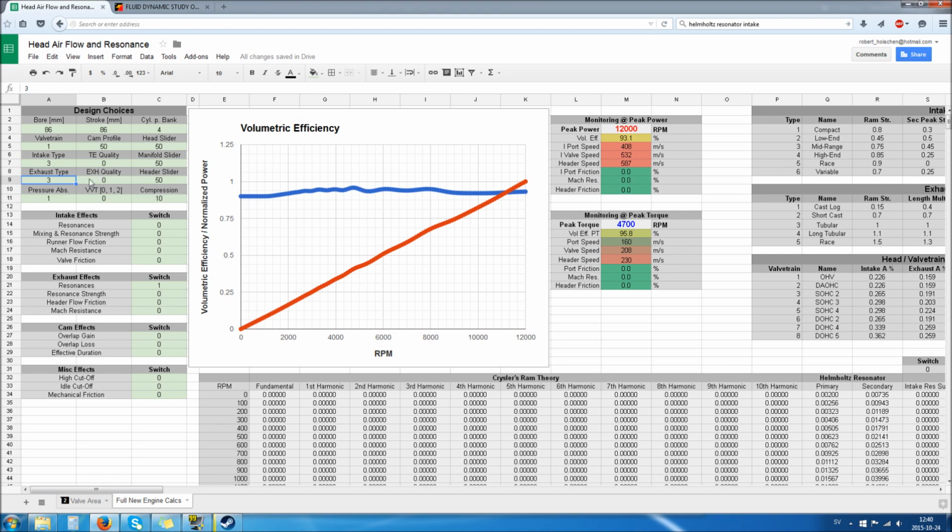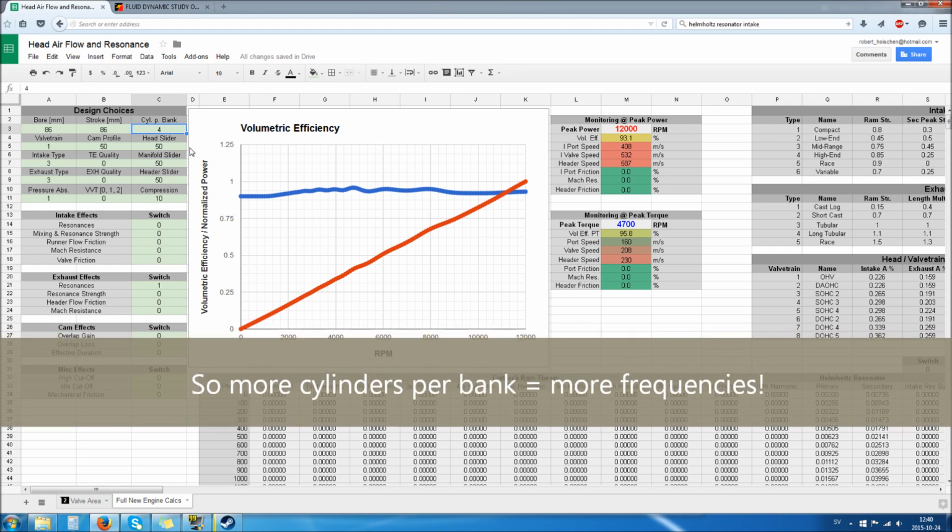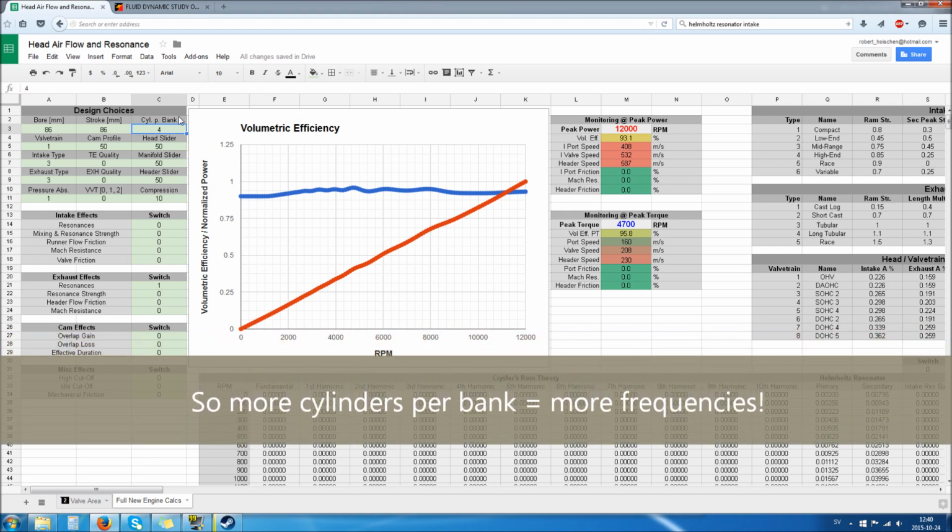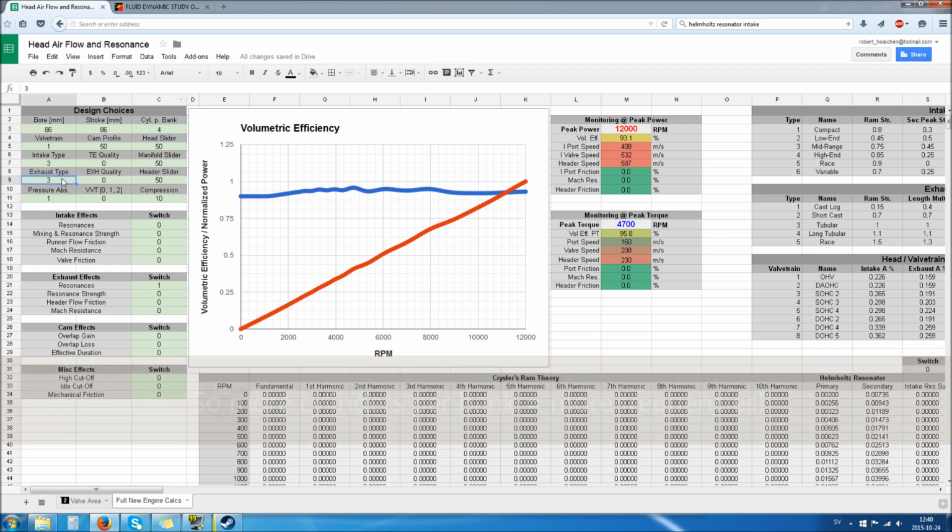Overall, that all works out pretty neatly, and an interesting effect we see here is this is 4 cylinders per bank, and like I said, the main pulse is not only traveling back in the main pipe, but also in the others, and helping to suck exhaust gases out of the cylinder if timed correctly. That is why race exhausts, these pretzel exhausts like type 5, have such powerful resonances at some of the frequencies. They are equal length and really designed to peak that performance and suck the exhaust gases out of the cylinder as soon as the exhaust valve opens.